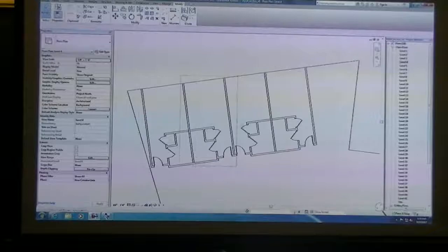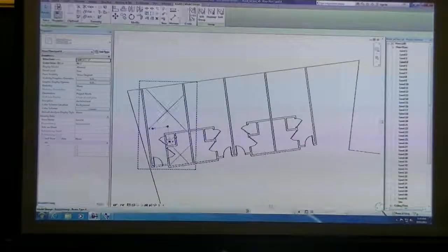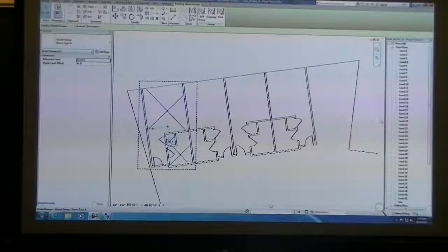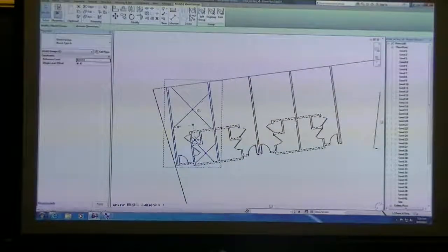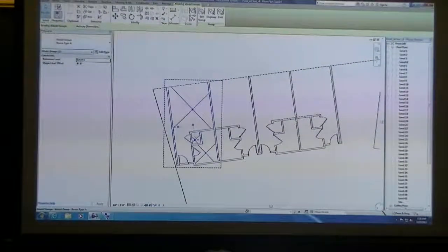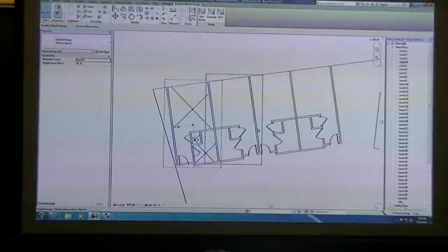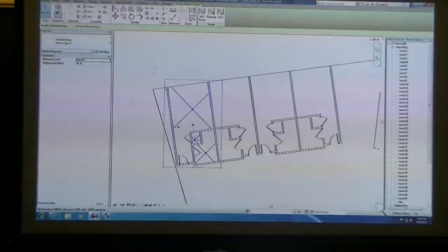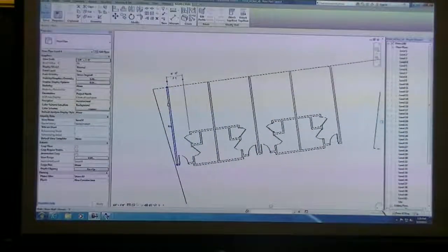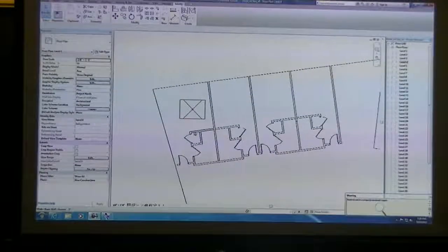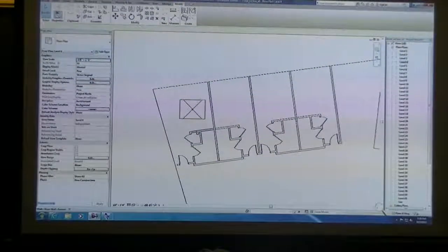And now when I get to this end unit, I know that I have to ungroup it to get rid of that wall. Or the other thing would be I could model this group so that I never have a wall right there, because I always know I'm going to end up with another wall on the other side based on this other group. Actually, no, you wouldn't. You do need that wall, so never mind. So now when I ungroup it and I delete this wall, I took away the group.